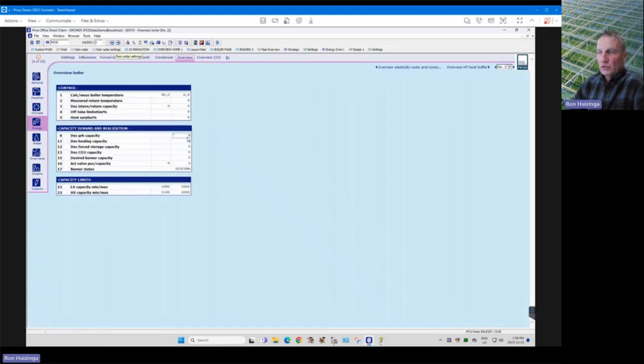So it's good in one way, that you get enough heat into your greenhouse. The bad thing is, of course, your boiler is going to be running in the evening to supply heat to the greenhouse, and you're not going to be getting any emptying of your buffer tank. So you won't have enough room for CO2 the next morning if your buffer tank doesn't empty out.